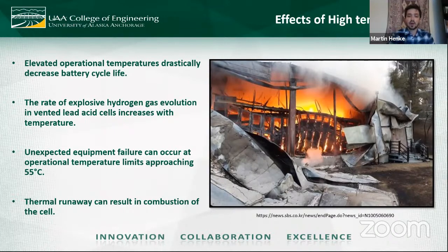On the previous slide, you saw that as temperature increases, so does voltage. Well, as voltage increases, so does the rate of discharge, which results in more heat being generated and the temperature increasing. So it's really a positive feedback loop where the temperature results in a higher voltage results in a higher temperature, and these two spiral out of control until combustion or explosion can happen. And it's really the reason you might have trouble receiving a lithium ion battery through the mail.